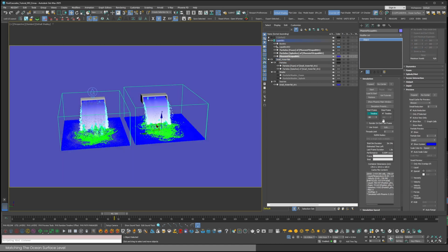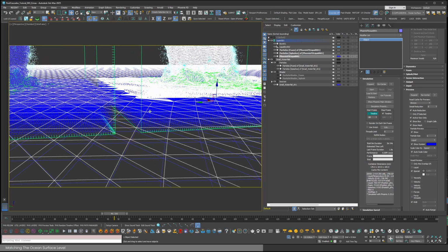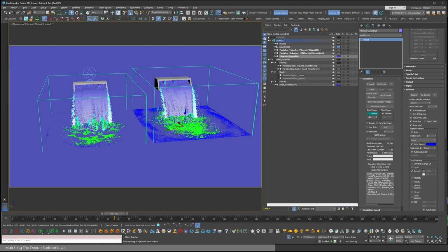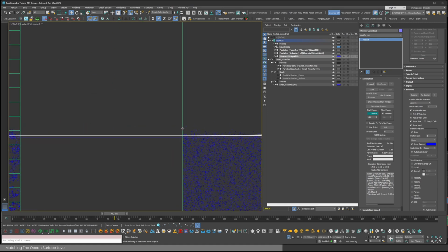I'll do the same thing for the other container. In the viewport, you won't see them as one combined surface, but as two separate meshes. The merge happens at render time when the actual full-resolution surface is created. In the viewport, you only see a low-res preview, and you can also see that they are misaligned. You can go into the side view again and bring them closer together. And yes, at minus 1.5 centimeters for the taller container, they are pretty close.